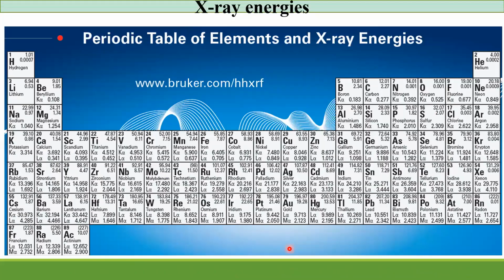But before going into X-ray analysis or EDS analysis, you should remember this periodic table with X-ray energies, because this is important. For example, you have a K shell energy of 6.74 and an L energy of 0.75 in the case of iron, and in the case of nickel this varies, and cobalt has other variations.